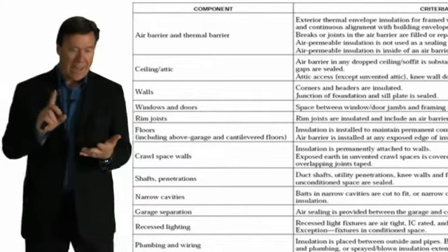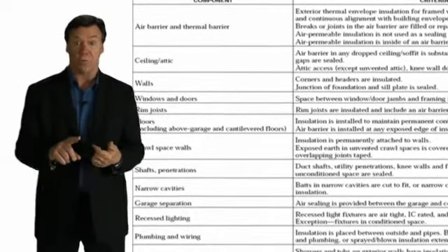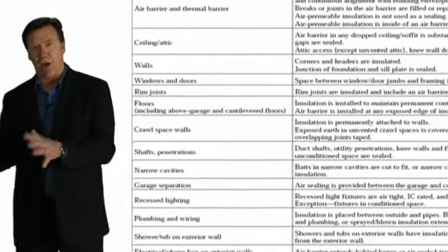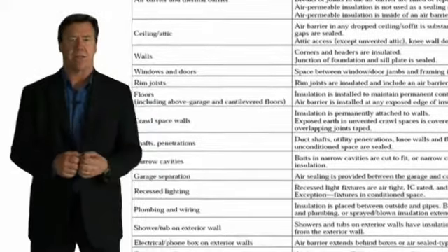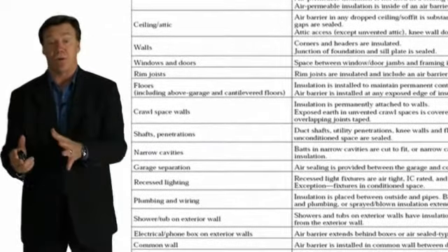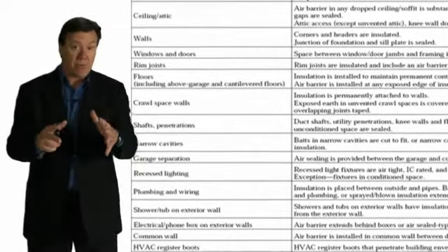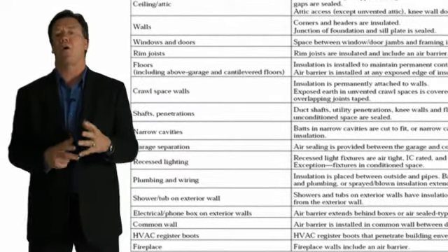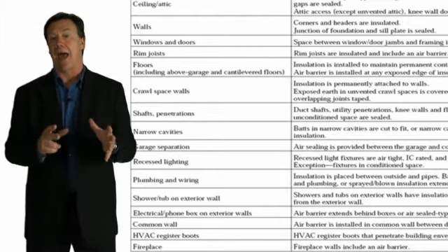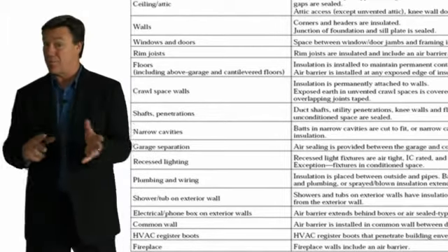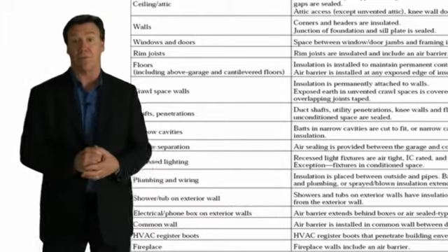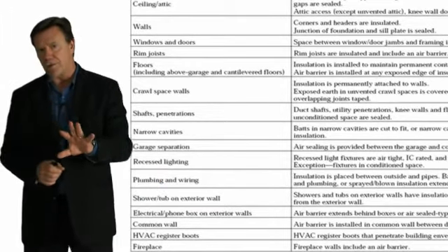So we're looking at attics and ceilings, walls, rim joists, the interfaces between shower tubs and exterior walls and fireplaces, between windows and door jambs and the frames around windows and the framing materials, with the goal to seal up all these unnecessary cracks and gaps that not only lead to air infiltration and exfiltration, but also are pathways for warm, humid air to infiltrate into the wall system.